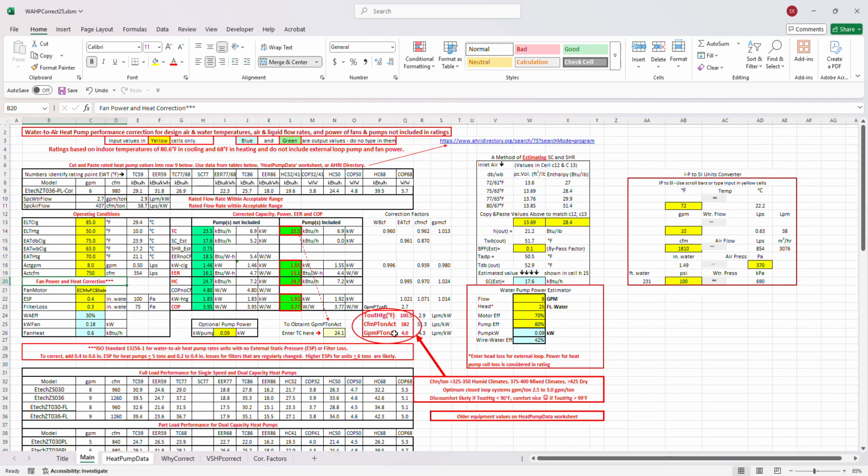It got us down to 382 CFM per ton and 100.5 coming out of the machine, and our sensible heat ratio is 75. So that did the trick. I'm going to have to change this up a little bit to match. Okay, so we're a little high on the airflow, but everything's looking good in terms of the sensible heat ratio and the temperature coming out.